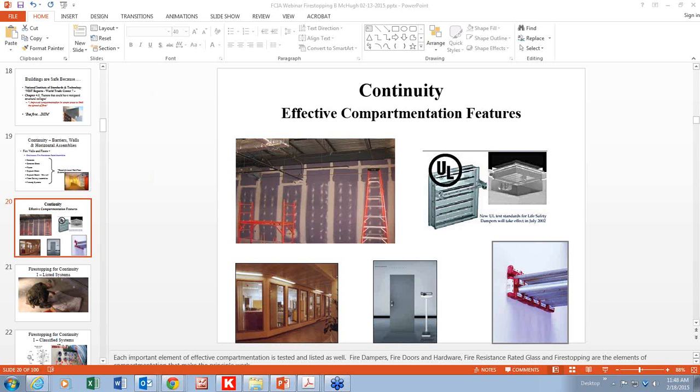And this also applies for Canada, because in Canada, the fire separation, which is what a fire barrier is called, is also required to resist the passage of smoke in certain situations, and a fire separation may or may not have a fire resistance rating. So we've got both conditions, whether you're in the U.S., Canada, or the UAE. So the question is, do I need to use a Firestop system with an L rating in a smoke partition which is not rated? I would say yes, you do need to use an L-rated Firestop system.